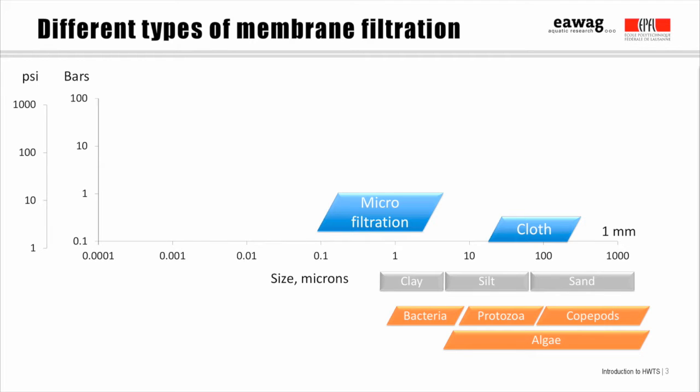Microfiltration will usually remove protozoa, like Cryptosporidium and Giardia, and depending on the membrane, may also remove bacteria, like E. coli and Shigella. Viruses and chemicals would not be removed, except the fraction retained on larger particles or adsorbed onto the membrane surface.